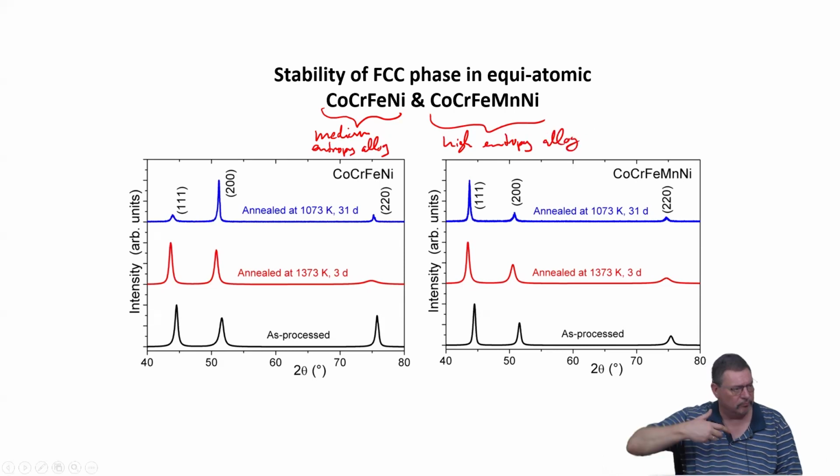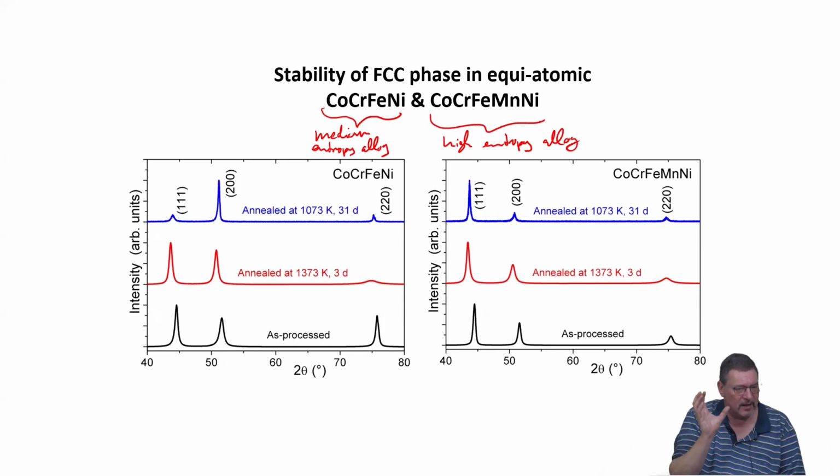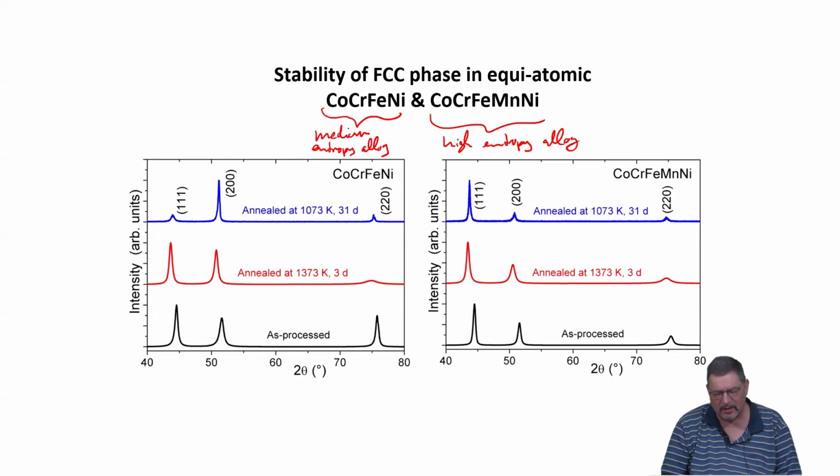And it's necessary to anneal both systems at specific temperatures in order to induce diffusion. So we basically need to be sure that we are comparing the same things. We need to know the phase composition of both alloys, medium and high entropy system, at each temperature where we are studying them. And these X-ray results show nicely and confirm that for these specific choices of alloys at the annealing temperatures chosen, both would be single-phase solid solution.